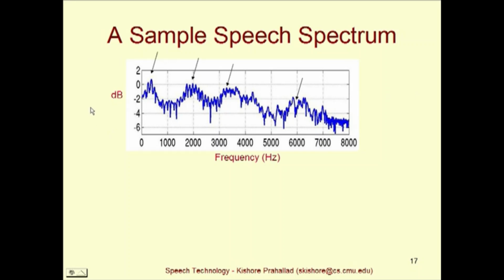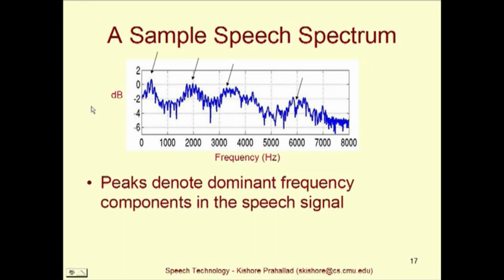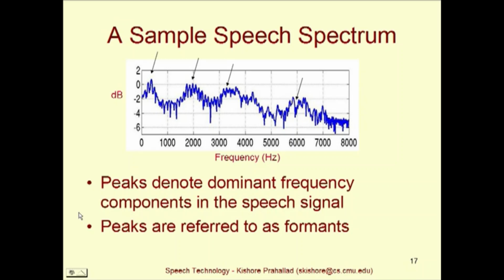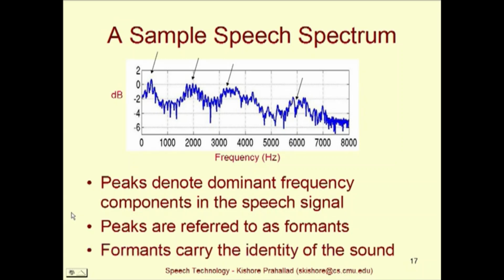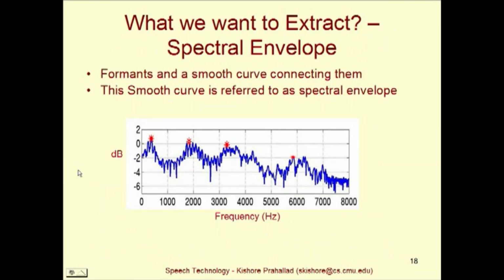Again, we have been emphasizing that peaks are important. Peaks denote dominant frequency components in the speech signal, and these peaks are referred to as formants, and formants carry the identity of the sound. So what we want to extract from the spectrum here is the peaks, correct, and at the same time we also want a smooth curve connecting these formants, something like this. So our goal is to extract